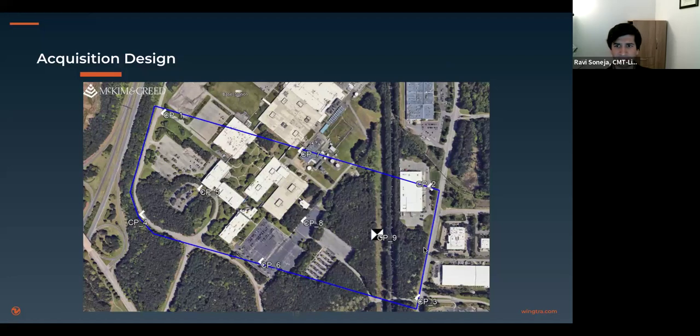And then as far as the actual control points, they were established with a 180 epoch observation the day prior to acquisition, and then revisited again the day of acquisition and observed again for 180 epochs. All those coordinates that we derived are left in grid. We're not changing any of those around or moving them to a ground in any way.